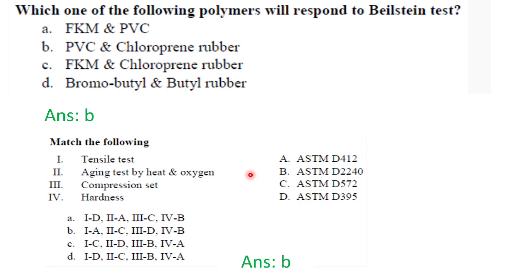And also I want to inform you one thing, that for a specific test, like if you need to do some ozone test, you must have a specific conditioned room to prepare the test pieces, and before doing the test you have to keep them in that specific conditioned room, otherwise the property will be different.